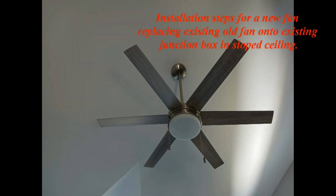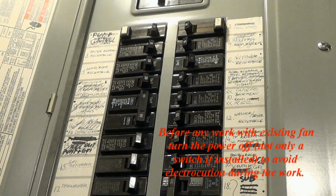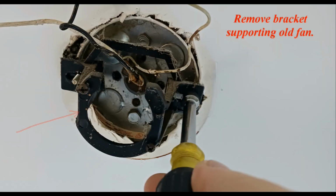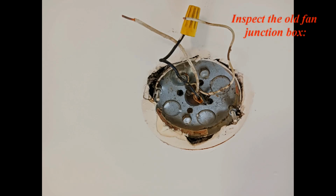Installation steps for a new fan replacing an existing old fan onto an existing junction box in a slope ceiling. Before any work with the existing fan, turn the power off, not only a switch if installed, to avoid electrocution during the work. Disconnect and remove the old paddle fan. Remove the bracket supporting the old fan. Inspect the old fan junction box.